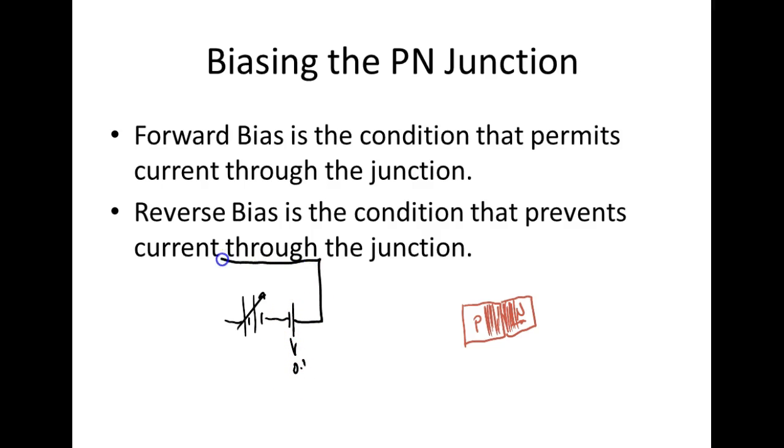And I come up here and do this. Well, if I'm sitting down here at 0.3, then basically this guy can't provide current, but this guy can't push against it, right? You understand that? So how much current flow would we have? Well, we're not going to have any if this was a diode. Now, in real life, we would have a little bit. If these were two real batteries, we would be pushing from left to right. But this is a battery, this is not. So the diode cannot push, right? You understand? So I come up here and I get this at 0.8 volts.